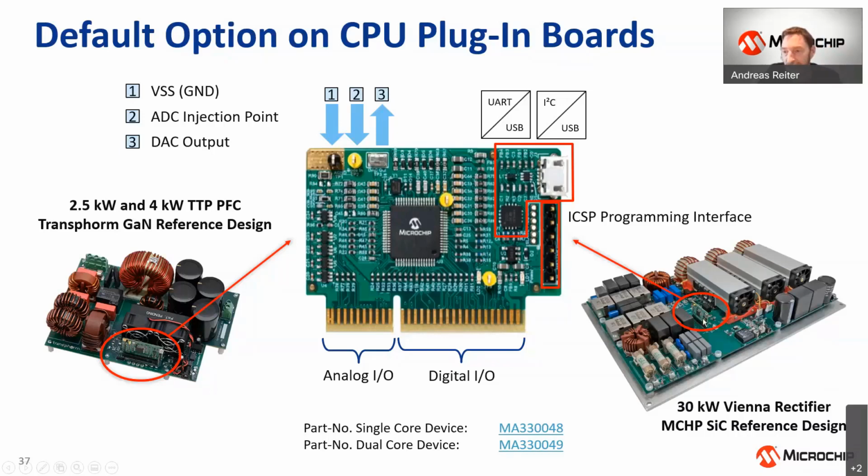So it is quite cumbersome to perform any direct work on the design. Again, when you have a decent interface, which is nicely accessible, the whole region on the board is free, can be isolated and protected for the probes, and then you just access your low voltage pins and perform your measurements.